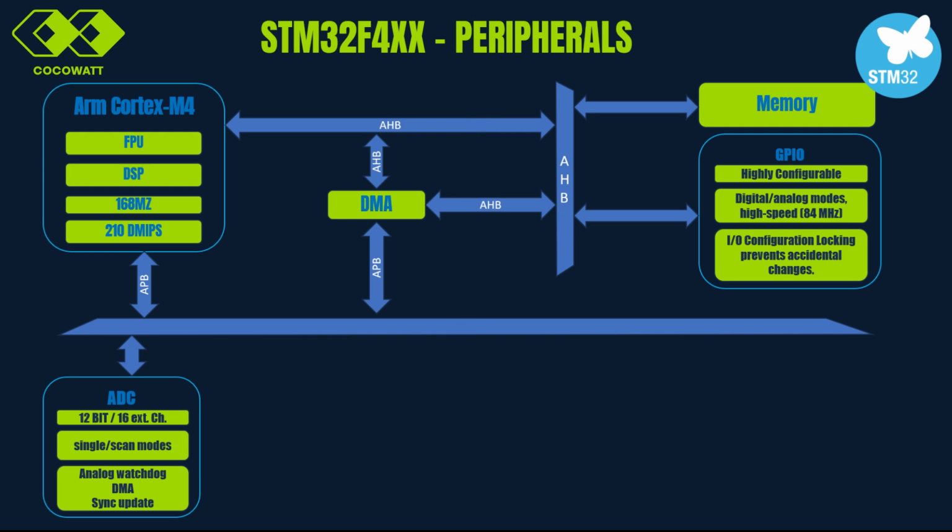It offers multiple modes of operation, including single-shot mode for converting one channel at a time, and scan mode for automatically converting a group of selected channels. And Watchdog is available for monitoring specific analog channels. It supports DMA for efficient data transfer and timer synchronization for precise timing.